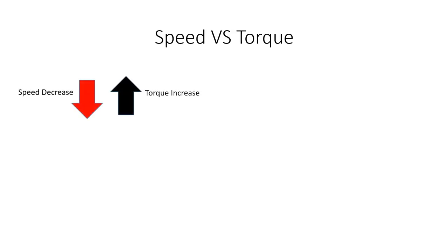When the rotational speed of your gearing system decreases going from one gear to the other, so you have a high speed input gear and you're getting a lower speed on your output gear, you're going to see a decrease in the torque. And you can calculate this well before you start to build anything. This is part of your calculation. Again, assuming the diametral pitch is the same, you will also be able to use the teeth on both sets of gears to find this.